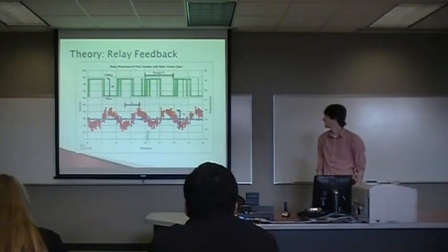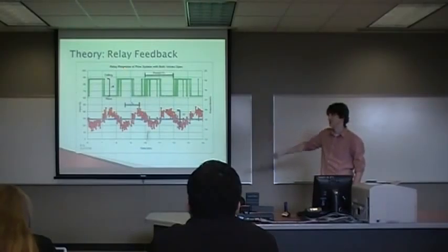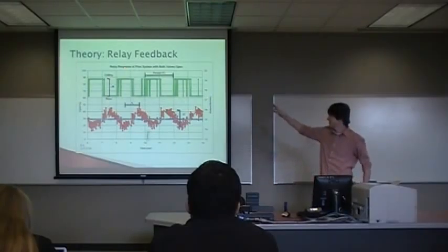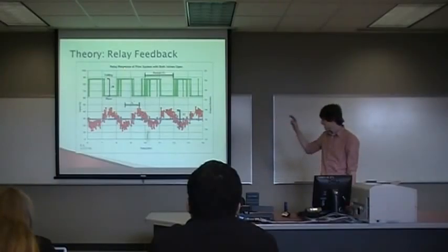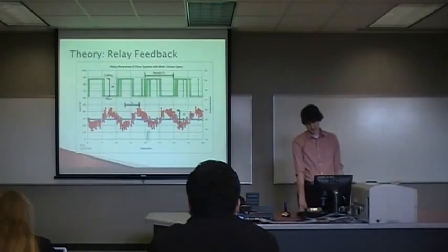T1, little t, is the difference between the midpoint of the ceiling and the peak of the red line, which is the output, in pounds per minute. And as the input oscillates between the ceiling and floor, the red line, or the output, also oscillates. The height to the floor of the output is delta C, and the blue line represents the set point value that was set at 15 pounds per minute and remaining constant.